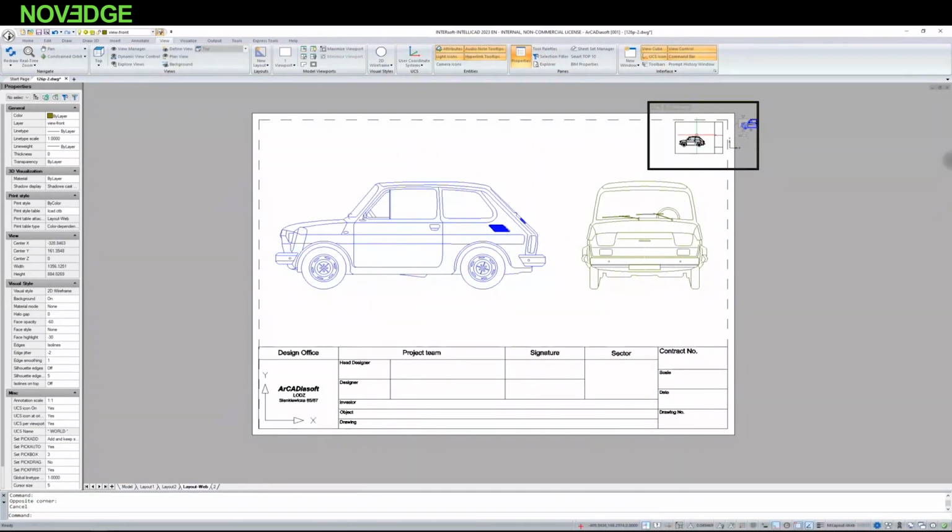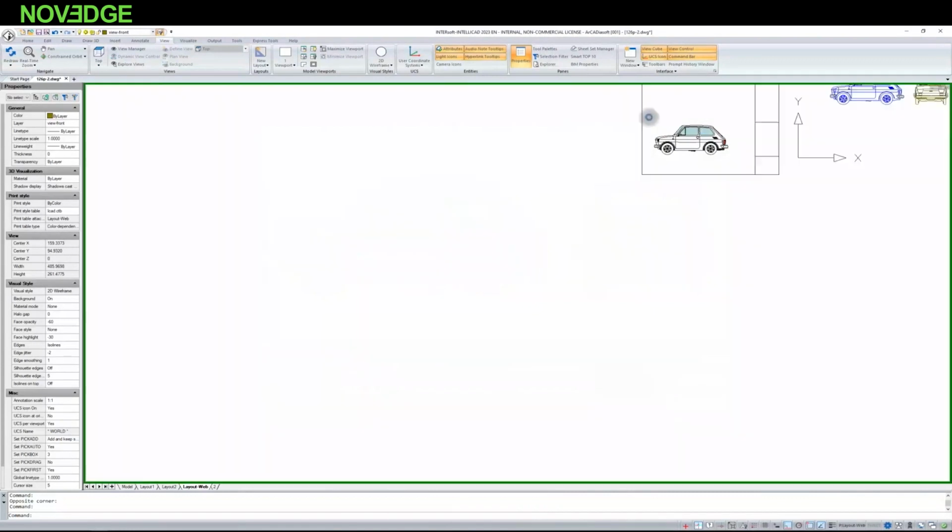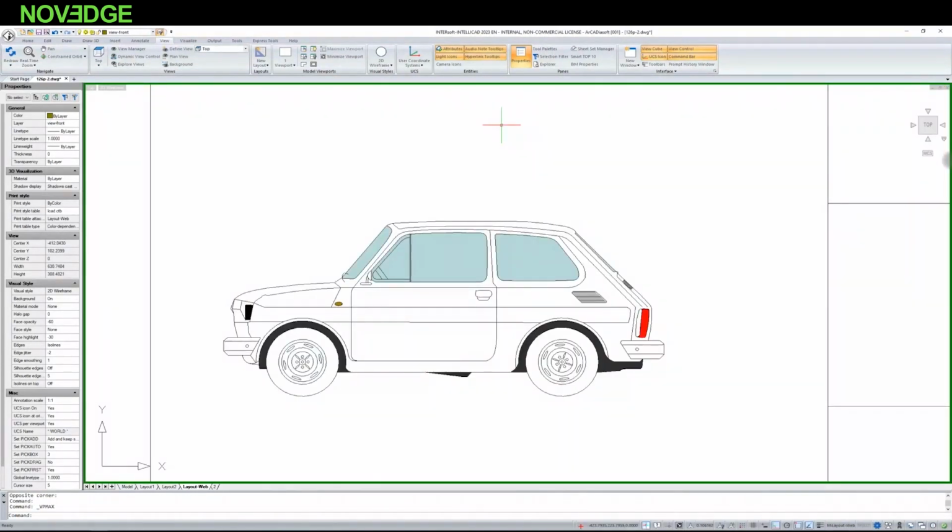This is exactly the same as clicking on the status bar at the bottom as I showed earlier. But please note that if I click on that part that is accessible to both viewports, it is uncertain which one will be selected. That's why we have the option to lock viewports. However, sometimes it happens that while clicking on the viewport, we accidentally click on the viewport border, and then the viewport displays on the entire screen.